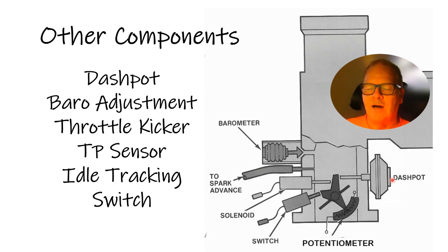And you'll say, why is my engine idling too fast? And if you look at your scan tool, it'll say part throttle. So you've got to fool around with those wires, because there may be something going on there, and when it comes back to closed throttle, it'll release that dash pot function. I've actually seen vehicle speed sensors malfunction and cause it to stay in the dash pot function, but that was an isolated thing that I saw on one car.